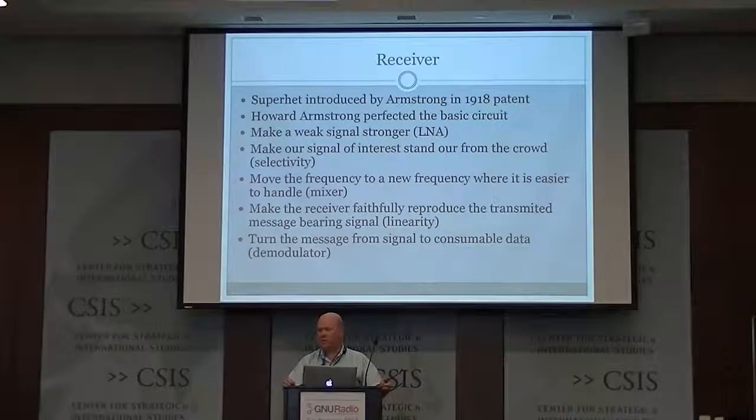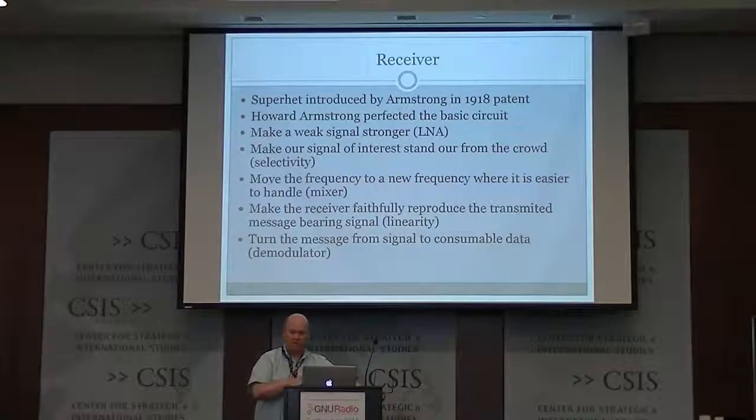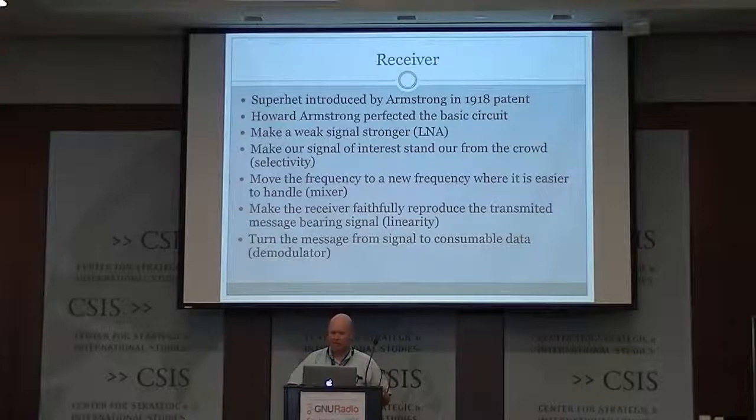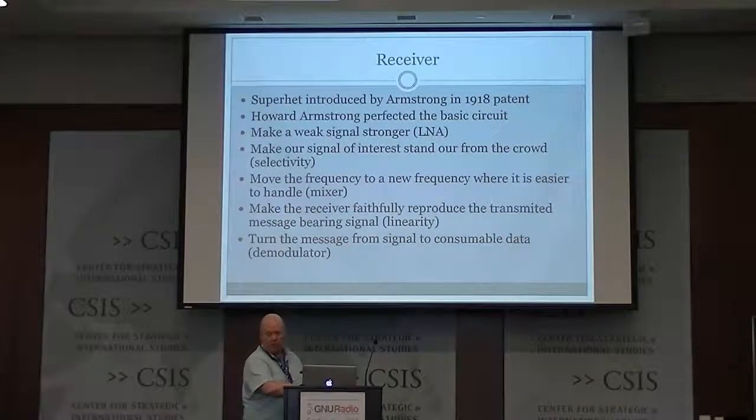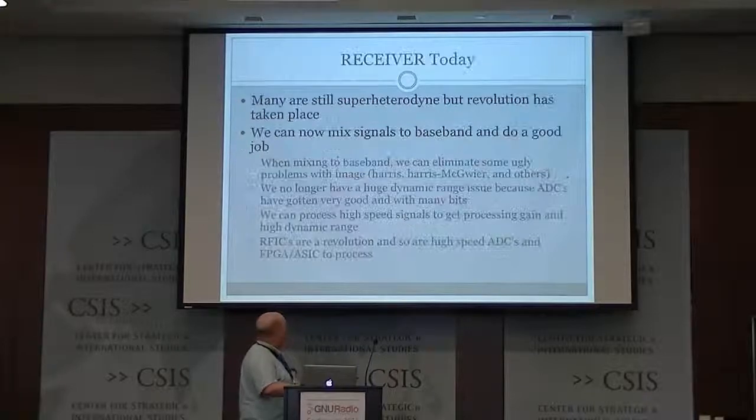What is that easy stuff called? Absolute value. So if I take the absolute value of an amplitude modulated signal, especially one that's brought down to near 0, I get AM out of it. Okay, so that's how an AM receiver works: I move it to some place where I have easy circuits, and then I just take the absolute value of the signal and have an AM demodulated signal. That's the crummy way of doing AM demodulation. There's a better way, we won't go over.